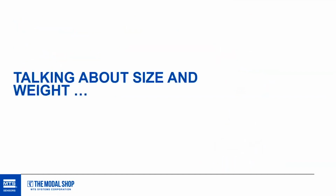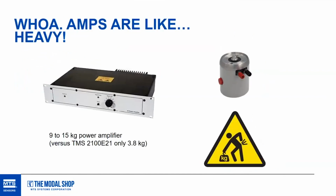Okay, talking about size and weight. We also had an interesting evolution when it comes to the amplifiers. So traditional shaker amplifiers were linear amplifiers. Nothing wrong with that. Those are good amplifiers, but they tend to be not as efficient, and so a lot of the energy is actually turned into heat instead of being delivered to the shaker.